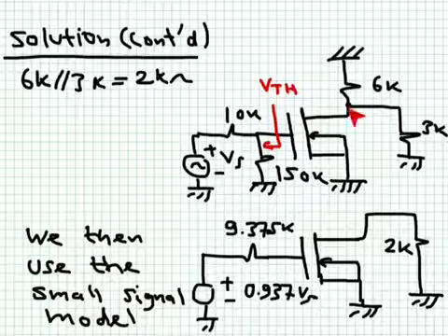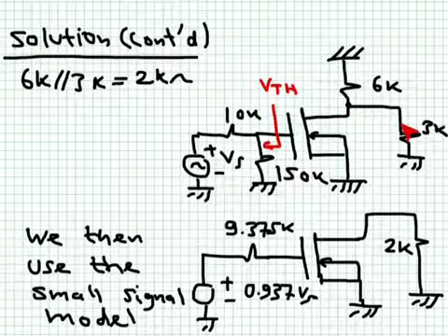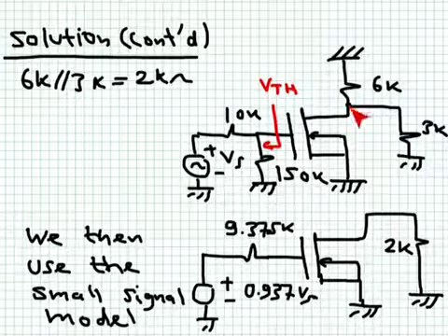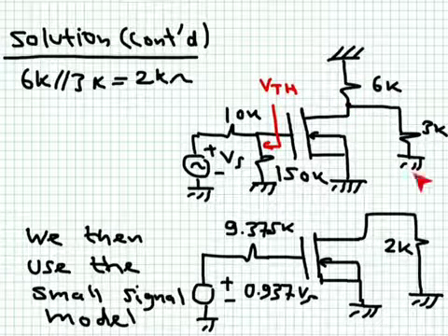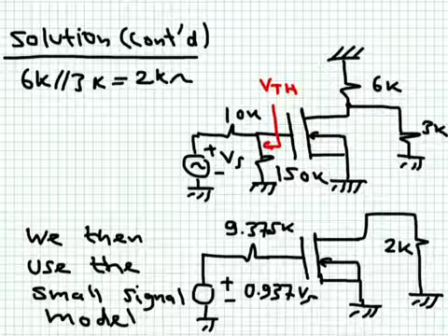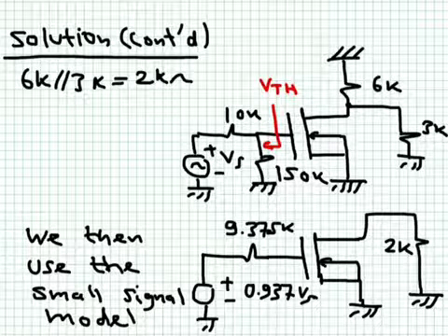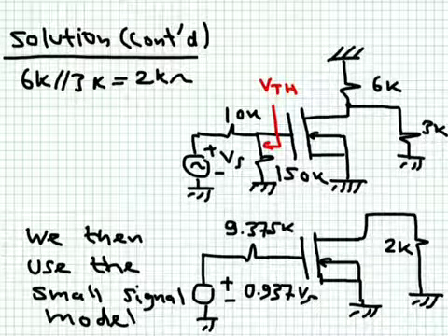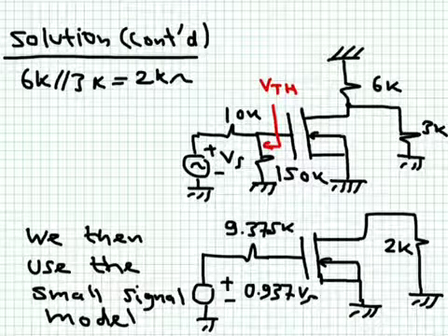So here you can see we have a load resistance of 3 kilo ohm from the drain to ground. We have this drain resistor, also connected from the drain to ground. So these two are in parallel. Their parallel combination, 3 in parallel with 3, is 3 by 3 over 3 plus 3, which will give you 2 kilo ohm. The same thing will happen here.